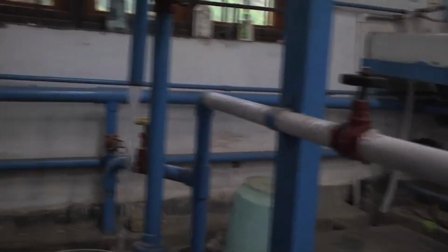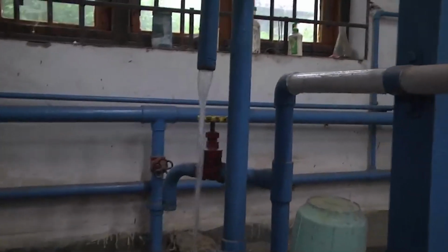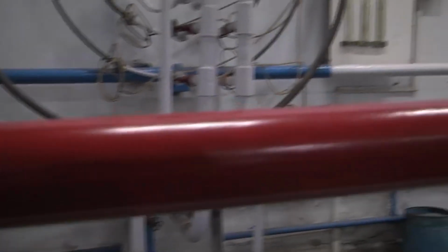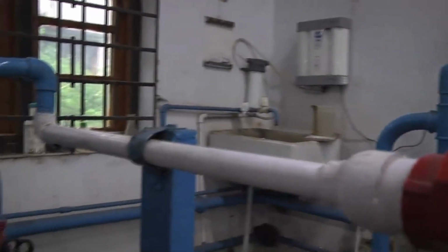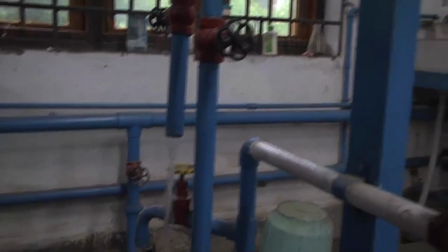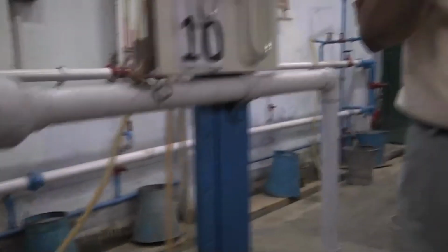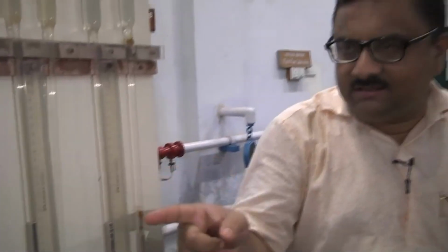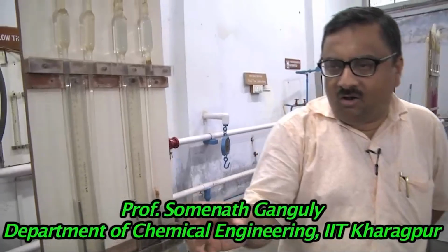So, now you can see that the water is flowing through this packed bed and is collected at the effluent end. The flow is taking place from this side towards that side, and is collected from the outlet. At the same time, we are making two types of measurements. One is the flow that is collected from that end, which can be measured in a graduated measuring cylinder or in a beaker and weighed. That weight is collected at regular intervals, and the interval is estimated by using a stopwatch.